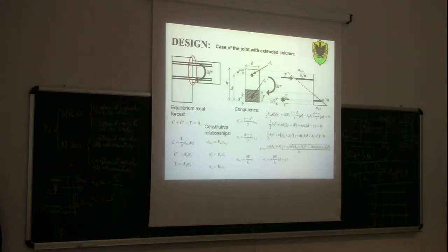So the sigma in the wood, the maximum compressive stress in the wood, is the bending moment M divided by the second moment of area of the homogenized cross section with respect to the neutral axis, times y, which is the distance of the neutral axis from the compressive fiber, and then for the steel we have this other equation here.